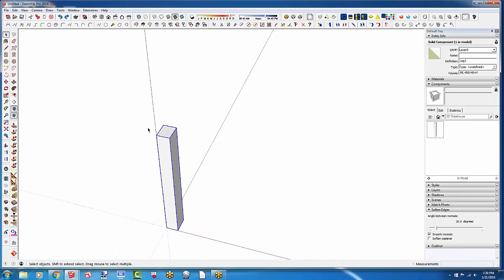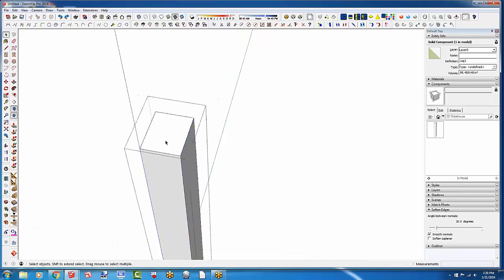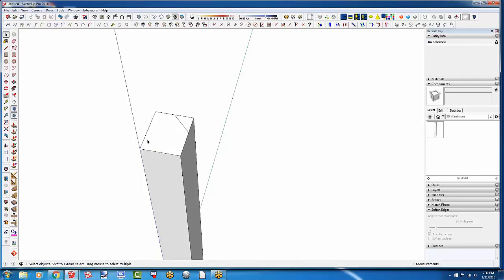Dave, if you make one unique, can you make it unique later? Not directly. What you end up doing is replacing the component. Let me do that, because there are 2 things there that are kind of useful. I'm going to draw a diagonal across the top of this leg, just to think of this as a cabinet maker's mark. If you have problems keeping track of orientation, you can put marks like this on, just like you would in the shop, to identify parts.